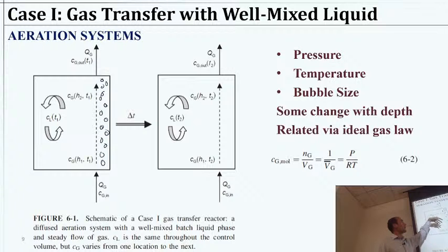The flow rate leaving of that gas should be pretty similar. Even if we have some transfer, it's usually going to be pretty small in the scheme of things. So it's usually the total volume or total flow rate of gas is approximately the same. So we'll say QG coming in and QG going out in that sense.